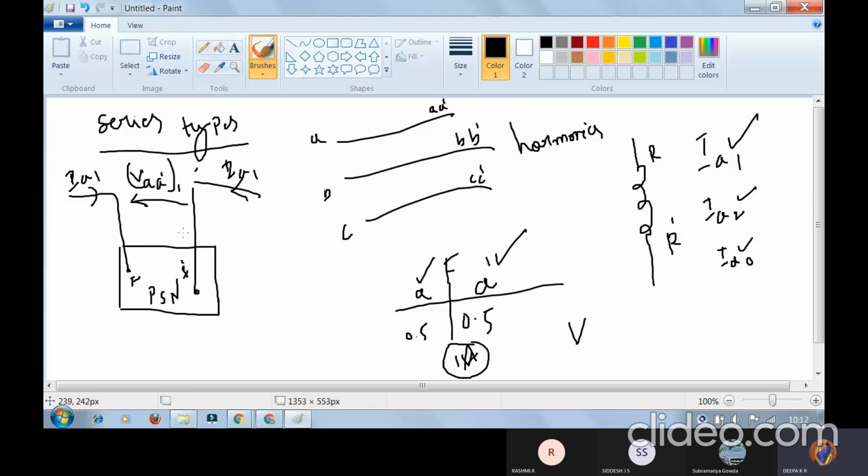Normally, as I said, various faults will occur: shunt faults and series faults. Among the unsymmetrical faults, we normally call one type open conductor faults. It can be one conductor or two conductors of a transmission line getting opened: B open, or B and C open, or only A open. Opening of a conductor means mechanical damage. A joint can be broken, or there may be malfunctioning of the fuses or protecting devices. We need to analyze the faults which exist in series with the transmission lines.